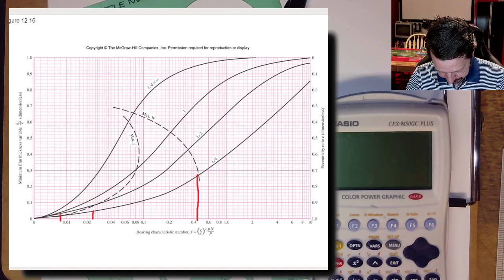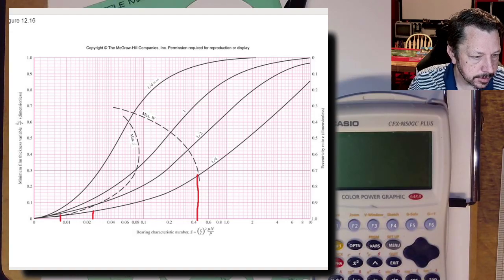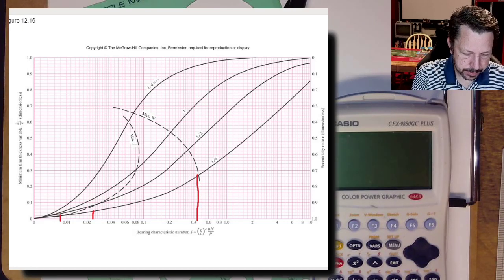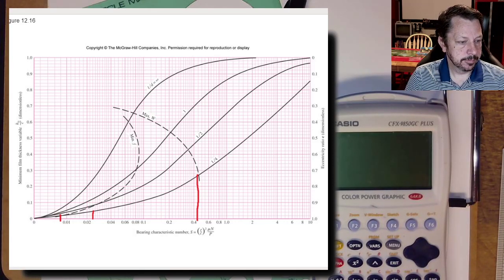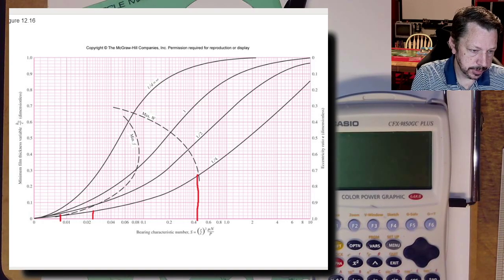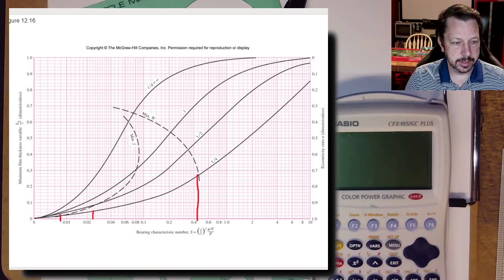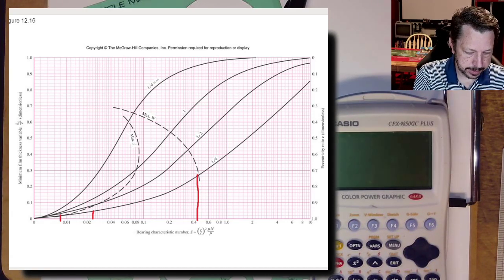Which is going to make all of my stuff from now on, because I see on my other chart where it did this before that I had a 0.05 in there. All right, so 0.5. We'll get all new numbers. That equals, well, let's do control equals H0. That is the minimum film thickness, but it equals this over C. So we actually have to solve for H0, which is not complicated, but I want to use Mathcad to do it anyway. So this guy is H0.